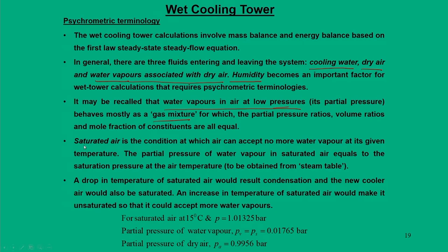So, there is a term which is called saturated air. Saturated air is a condition of air in which the air cannot accept any more water vapor at a given temperature. This can be obtained from the data tables in the steam table. That means, we all know that for every saturation temperature there is a saturation pressure and vice versa. Any drop in temperature of the saturated air will lead to condensation. So, the newly cooled air would also be saturated.